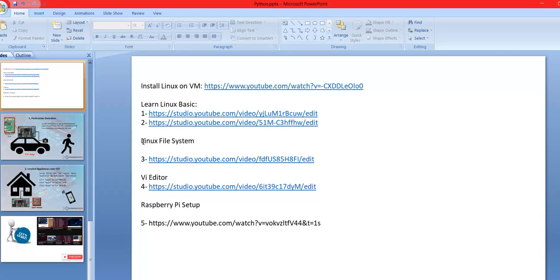Then it would be good if you can also explore this video, like what is the file system of Linux. That will be really helpful for you to understand the Linux directory structure. And then if you are going to use the vi editor, the Raspberry Pi board you can use in two modes. One is in the desktop environment, where you can connect monitor, keyboard, mouse, and you can use it as you are using your Windows machine. But if you want to use the Raspberry Pi board to build any gateway application, in that case you need to know how to do SSH on the Raspberry Pi board and how to use the vi editor.